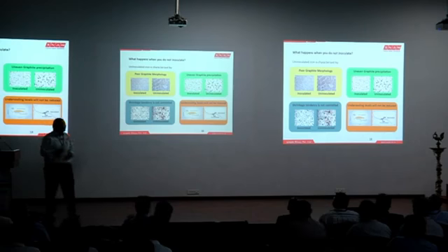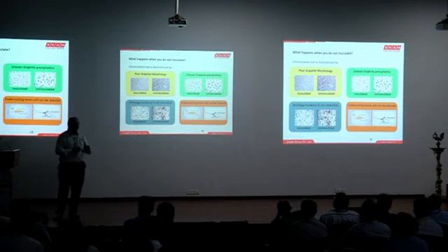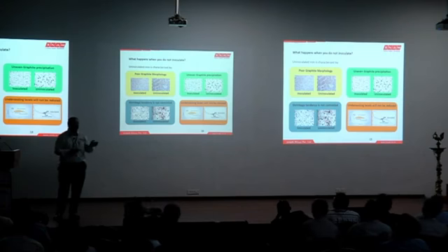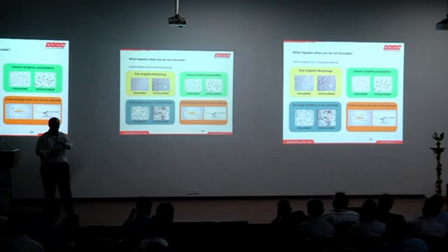So can I produce cast iron without inoculation? Yes, possible. But the problem is you will be lacking uniformity. It does not mean that if you don't add inoculant, you end up with 100% carbides. No. Your liquid metal by itself will have around 50 to 60% of the potency to produce enough graphitization. The problem is that because of varying section thickness, because of the cooling rate, and because of the profile of the casting, the same carbon equivalent works in a different way at different locations.